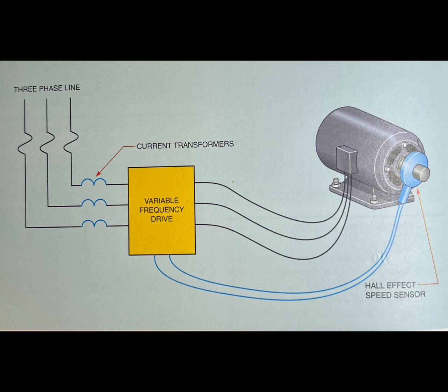Another feature of variable frequency drives is acceleration and deceleration control, sometimes called ramping. Ramping is used to accelerate or decelerate a motor over some period of time. Ramping allows the motor to bring the load up to speed slowly, as opposed to simply connecting the motor directly to the line. Even if the speed control is set to a maximum position, when the start button is pressed, ramping allows the motor to accelerate the load from 0 to its maximum RPM over several seconds.